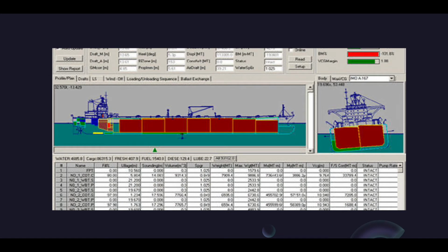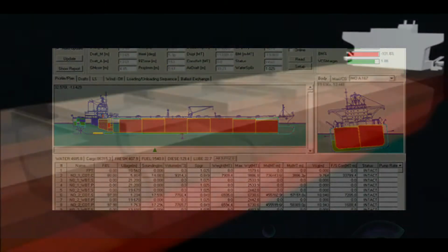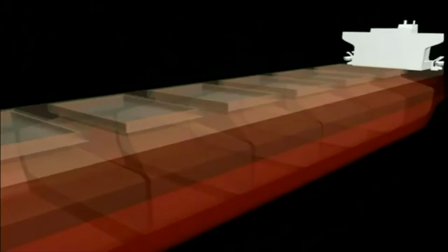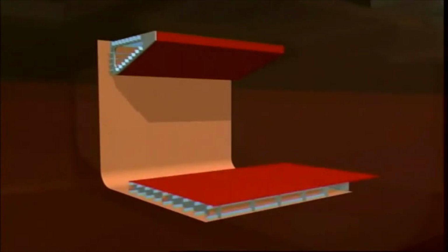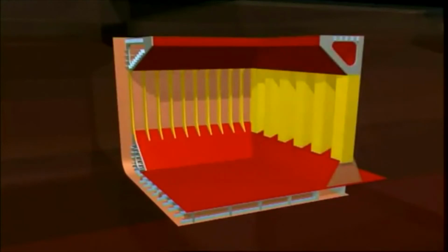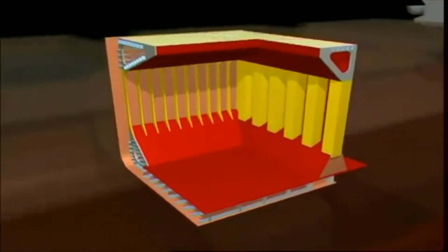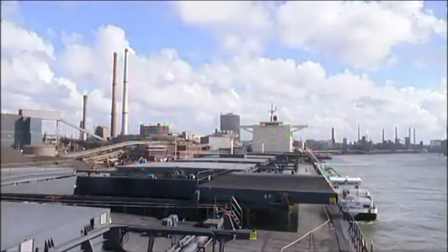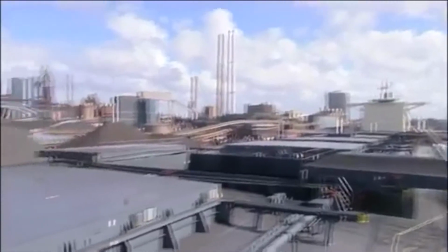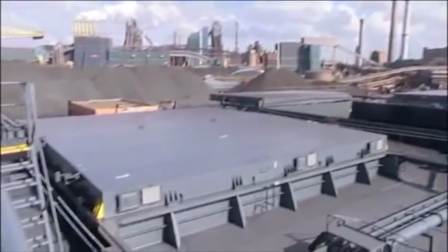And now let's continue with stowage plans of a ship. A stowage plan needs to meet multiple criteria. The structure of a typical bulk carrier consists of a single-deck ship, fitted with topside tanks, a double bottom, hopper tanks, and side shells with vertical frames, corrugated bulkheads, and hatchways above. The holds are a series of large spaces separated by transverse bulkheads.